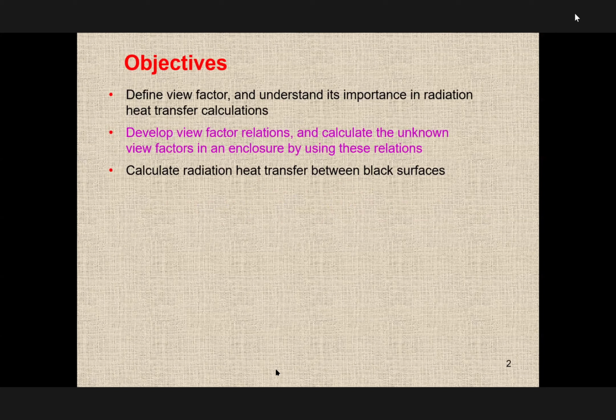As we discussed last lecture, we are trying to define the view factor. I'm sure you have some idea what that means because we covered it in building science, and we are going to review the 2 laws that we discussed. It was the reciprocity law and also the summation law, because we are using these 2 principles trying to find what fraction of energy leaves one surface and will be captured by the other one, okay? That's very, very important in the design of different types of systems, because you can minimize your energy by knowing exactly where energy has to go.